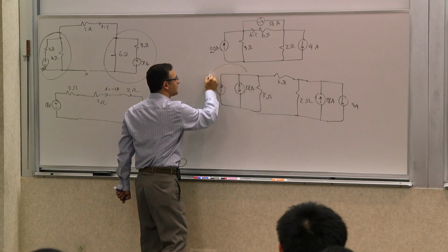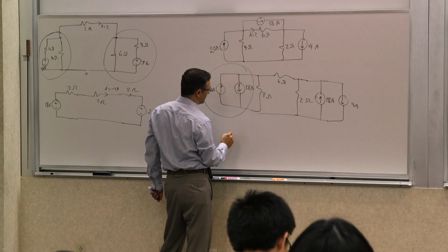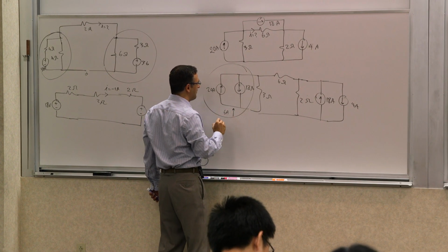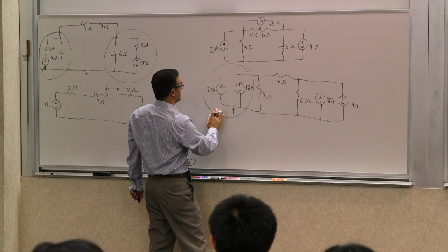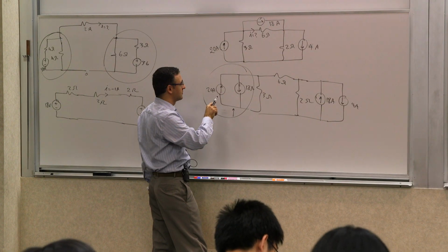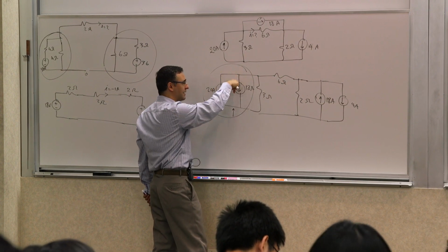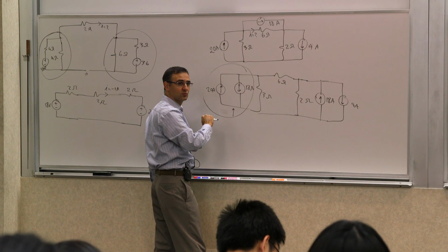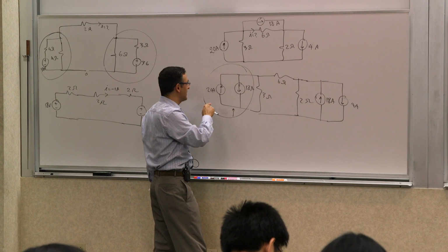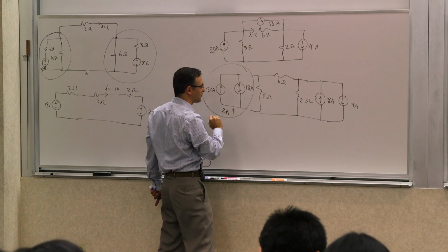So what is this? This is equivalent to a single current source of what value? 6, yeah. In which direction? Up? 6? No, sorry, not 6. This is 20 and 18. It's 20 amps up, 18 amps down. What is the current? This is 20, this is 18. 2, exactly, yeah. Sorry, if the font is too small.